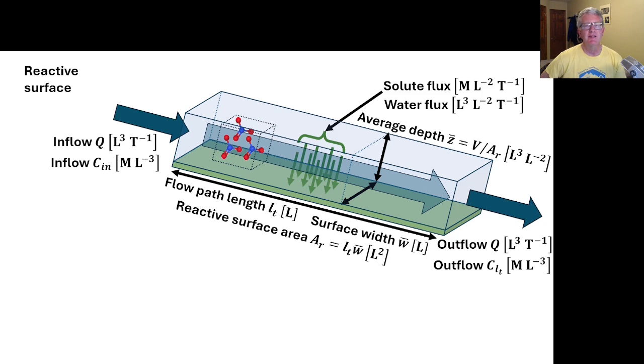The intrinsic effectiveness of the reactive surface is characterized by fluxes of either solute mass or water volume across that surface. Fluxes are defined dimensionally by the areal density of transfer of energy or matter per time. I cannot stress enough the importance of the per area in these dimensions for their proper interpretation. The fact that these metrics represent areal densities means that we have inherently lost information about the total amount of mass or volume transfer. Therefore, these metrics help us compare the behavior associated with an average square meter of the stream bed rather than the behavior of the stream as a whole.